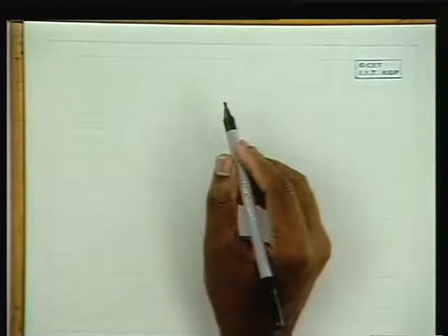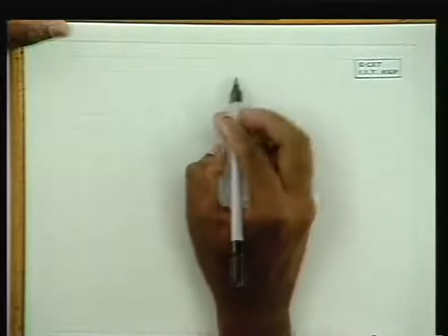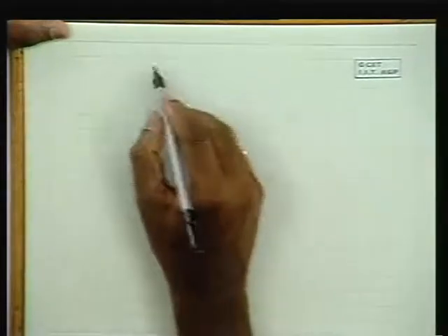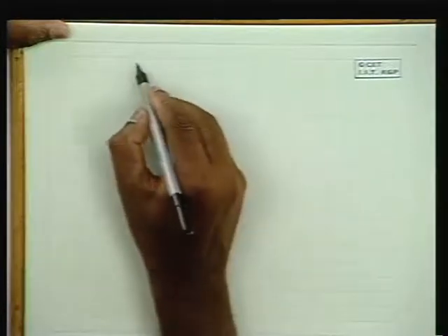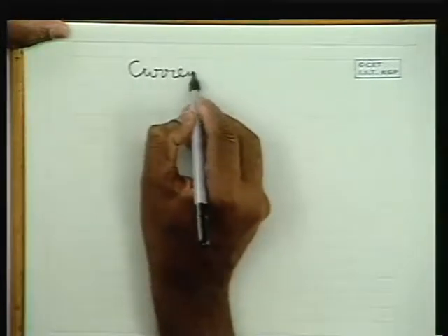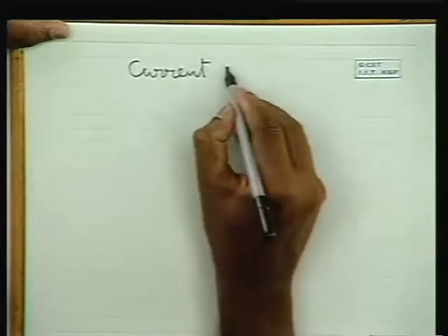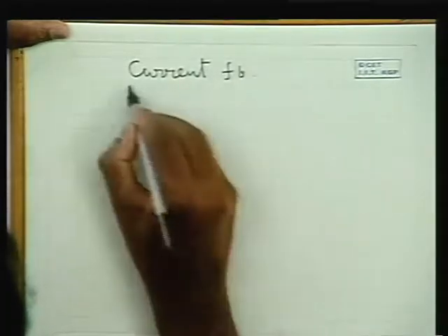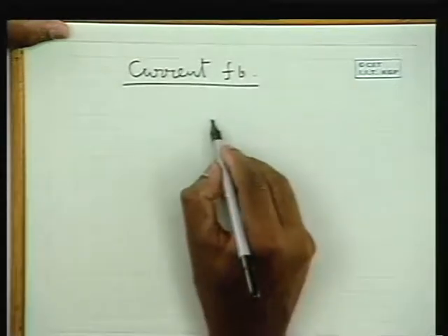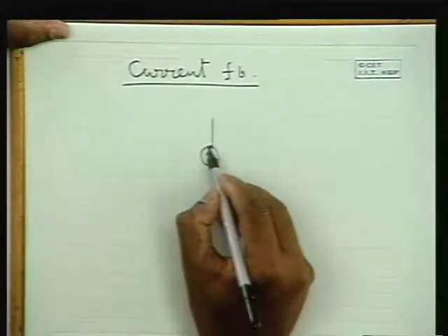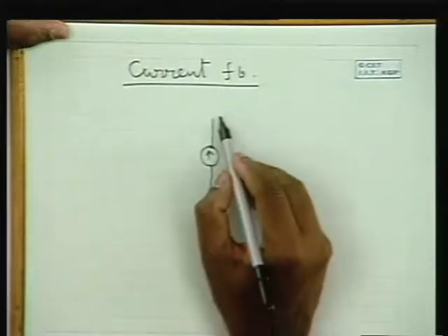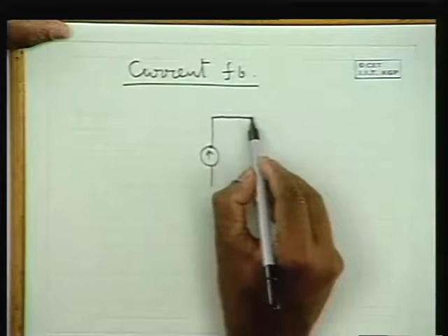Now we shall see the effect on output impedance when the connection is a series connection, when current sampling is done at the output for feedback purposes. So let us look at the output. If it is current sampling of the output signal, or current feedback, we tap the output current when the output signal is a current signal.